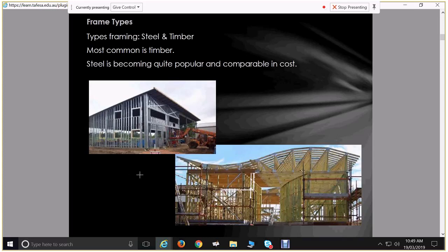Also, another thing that relates to that difference between the two: timber we can design with AS 1684, steel has to go to the manufacturer. A lot of your smaller scale designers, and when I say small scale, you can still have relatively large building companies, designers that work solely in timber, but a lot of your steel framing is done by larger housing companies, the bigger ones, because we don't have much control over that, we can't really do much bespoke design with it.